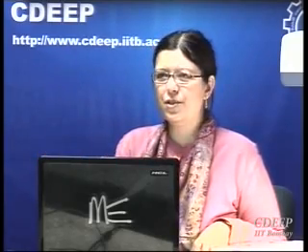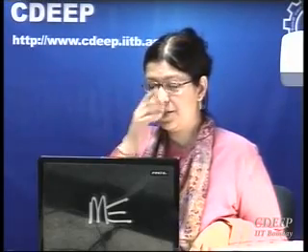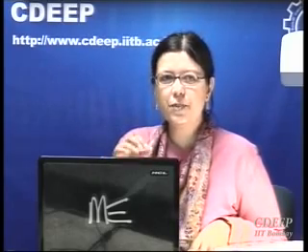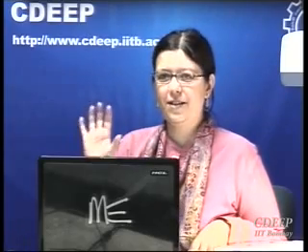For DAC also, you know the basics now, for example charge distribution DAC and other architectures like current steering. They are very straightforward, right? You have n current sources and then put switches, and the issues are similar in all of them. As I told you at the beginning, and now you understand, ADCs and DACs are very simple in concept. What makes the issue in their design is non-idealities, which are related to switching and related to mismatch and variability. So we will stop here, and from the next session I will start on PLL and DLL.